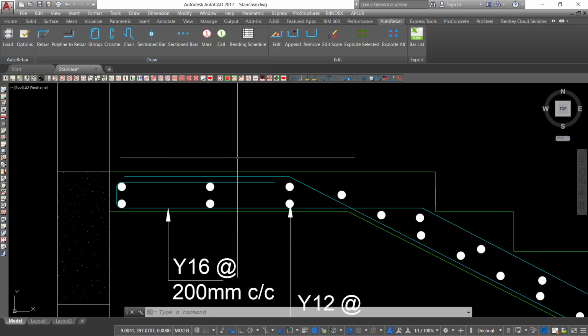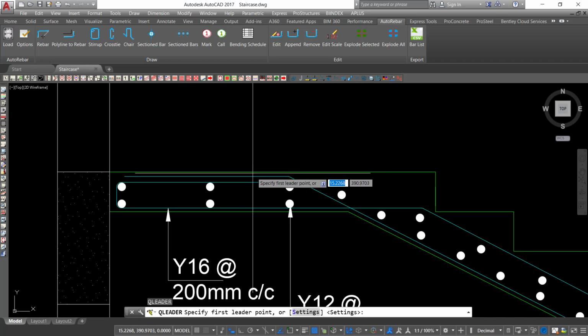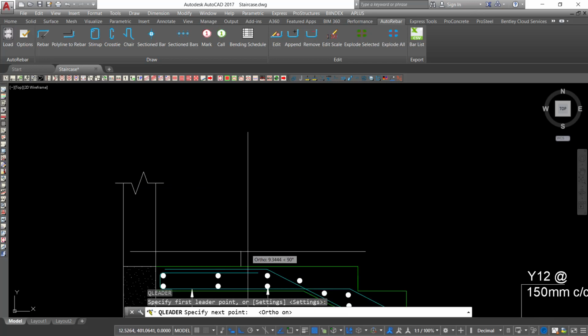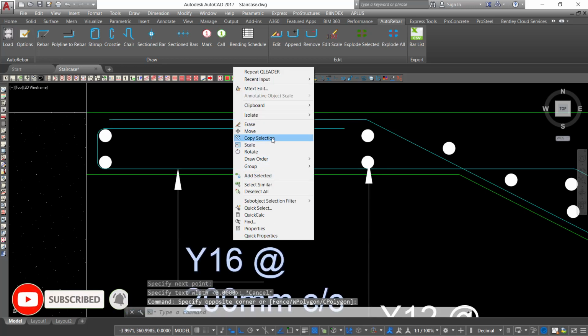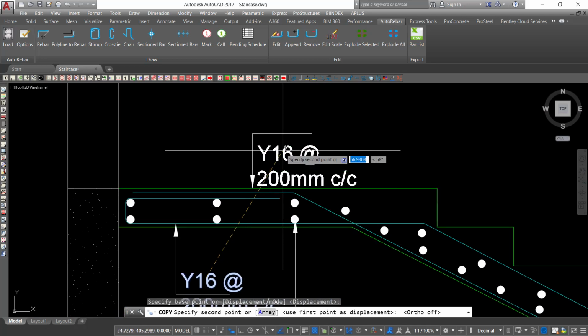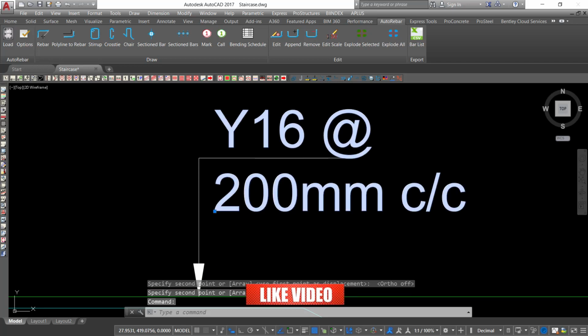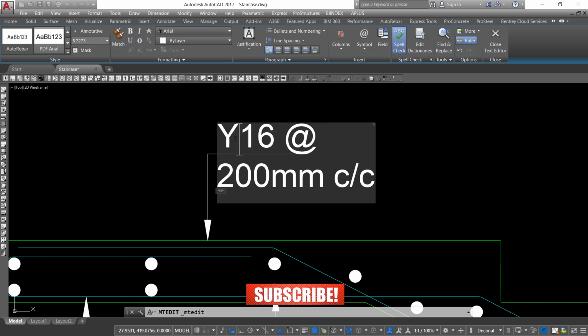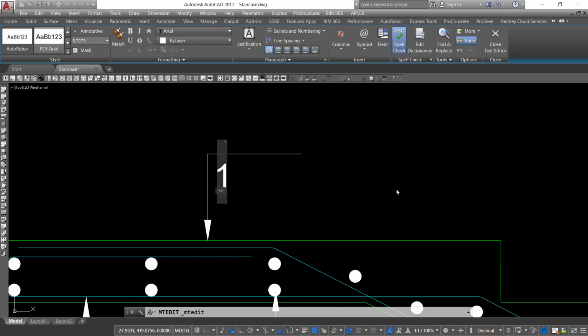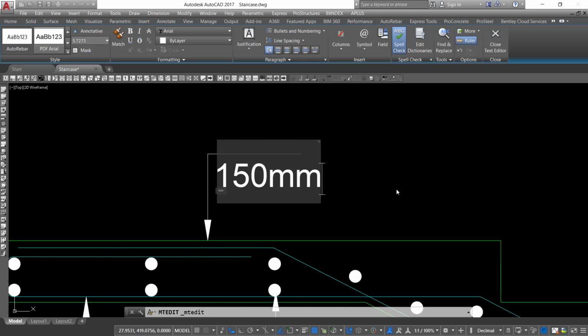So what I'm going to do, I'm going to just continue labeling up or detailing our staircase. So I'll label that as my first floor. So what I'm going to do, I'm going to use the same text and modify. Let's drag it up and place it somewhere here. Double click on it. So in here, I'm going to drag this slightly, or double click here. So this will be 150 millimeter thick slab. This will be thick RC.